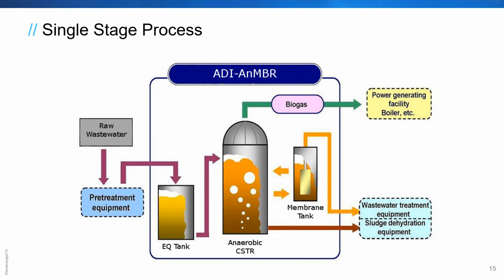they have some pre-treatment, which of course, those that are familiar with MBR, any MBR should have some sort of pre-treatment, especially on the screening side. Typically a perforated plate screen, 2 millimeter, 3 millimeter, depending on what the supplier requires, to protect those membranes from materials that can cause abrasion or clogging of the membranes. Followed by the equalization tank, which in any pilot or full-scale equalization is a good thing. As you probably know, membranes have, as a permanent barrier, a limit to how much flow range they can handle. So equalization helps dampen that peak that can be handled through the membranes.